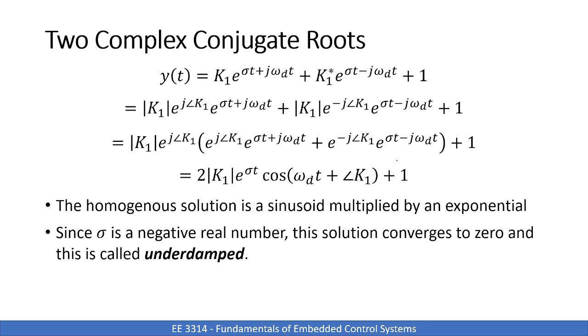And you'll see what we actually get is we factor out this decaying exponential. This becomes a sinusoidal term. So really what we get is an exponential and a sinusoidal term. This is why, if sigma is in the left half plane, this is going to decay, and this will be a decaying oscillation, right? So it'll look like that. Whereas if sigma is in the right half plane, in other words, if sigma is positive, then that is going to be exponentially increasing, which would be bad in general.